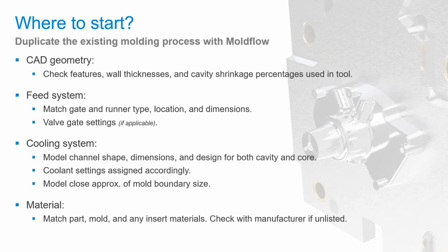So once you have an idea for what you're looking for Moldflow simulation to help with, the next step is to mimic the existing process, so you have a baseline to compare your experiments to. This can sometimes be a little tricky, as sometimes the settings may need some work to fit them into simulation, such as converting different units. And you'll hear me mention units a lot because that's something I remember from the support team often hearing.